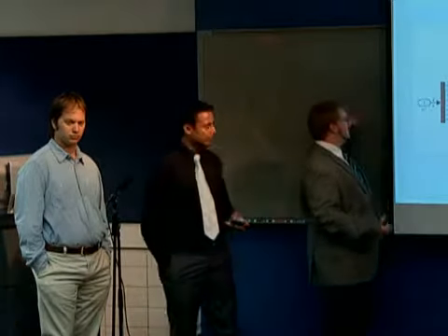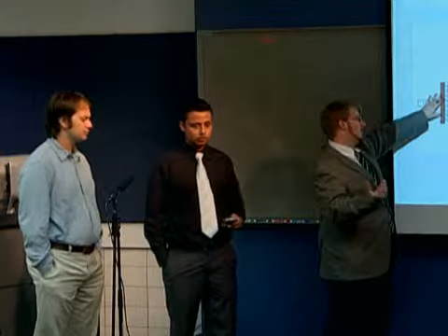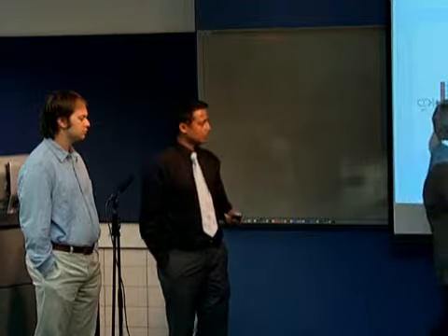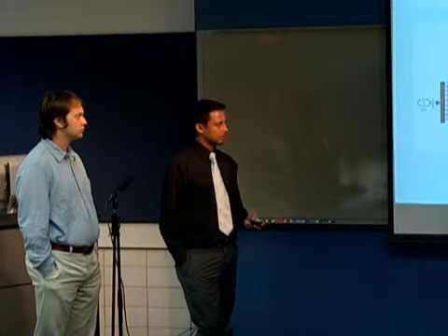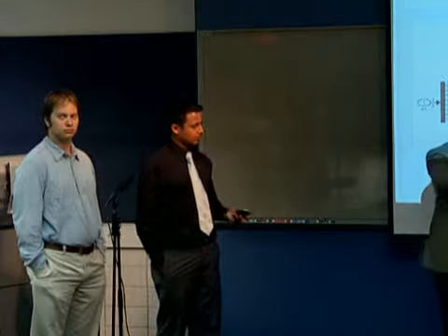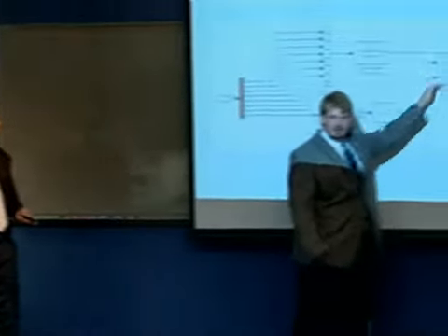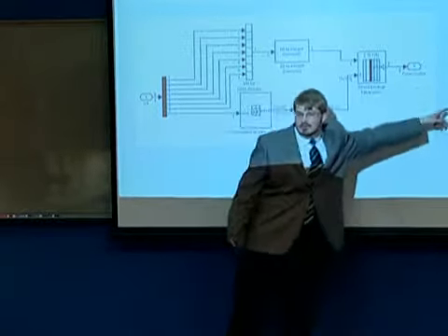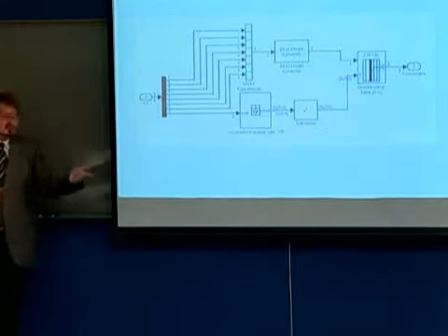Yes, so pretty much you get a binary sequence in that's 8, and then the convolution encoder adds redundancy to it, so that makes it 9. Also, what the convolution encoder does is output a particular subset into this lookup table, which is a list of all the possible coordinates within that subset, and then the rest of the bits index row-wise which one it should be, and that's what's outputted. Does that make sense? And that coordinate is 8-dimensional.